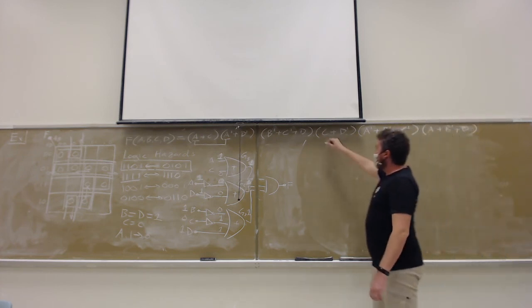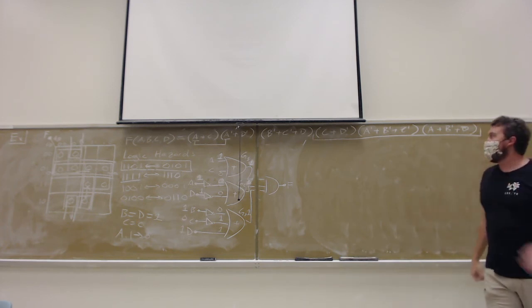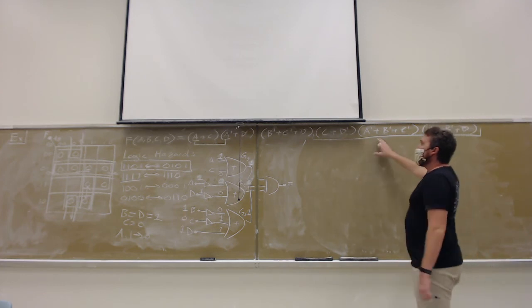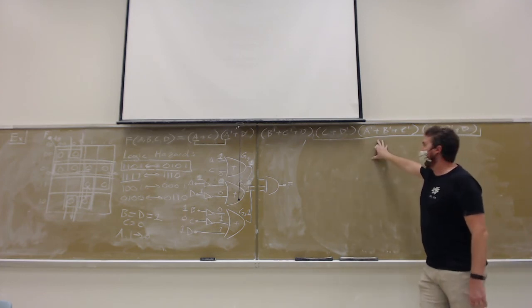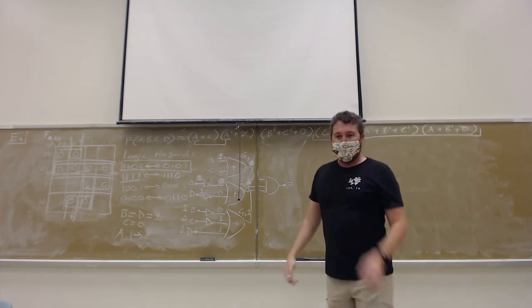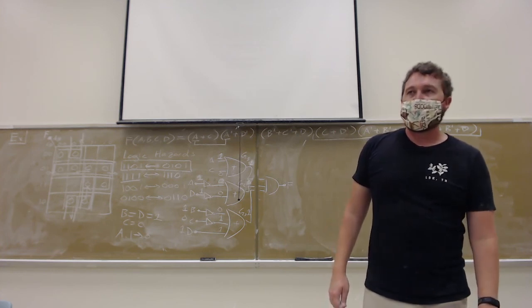So yeah, we added on 3 additional sum terms, which arguably adds a lot to our circuit, but it cuts out those logic hazards. And again, the decision of what is worthwhile, is it worth it to add these terms to cover the logic hazards, kind of depends on what the application is and what the consequences of the logic hazard are, right?